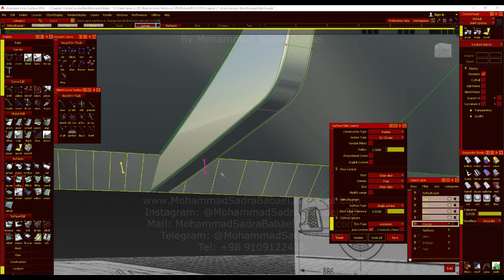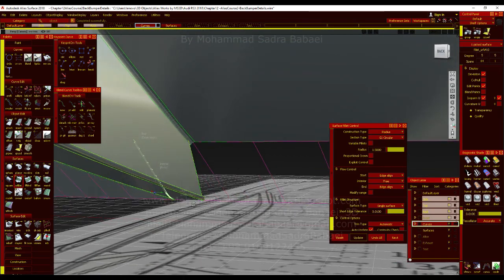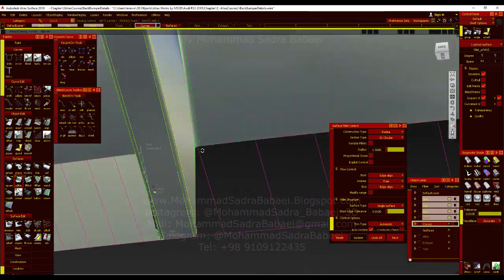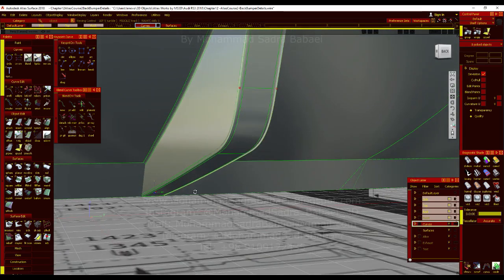Because why? Because that middle surface, I'm changing the arrows, it's not okay. As you see, it has a bad problem here because that middle surface is intersecting our initial surface positionally. So take care of that. You should add a fillet here manually if you want. Just clicking on these 2 surfaces.